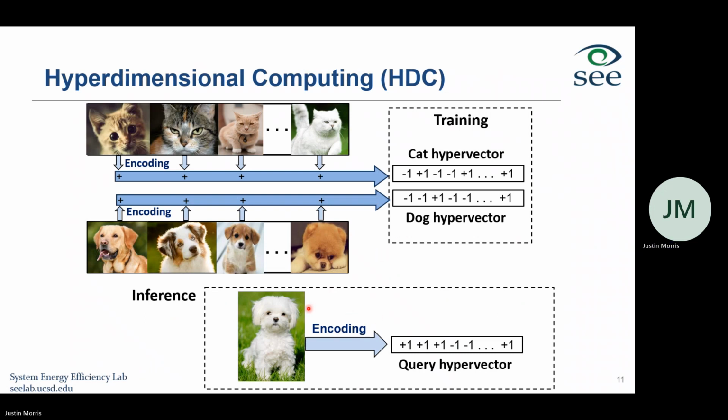So you just have the trained class hypervectors, and you need to load in some encoded query hypervector, and you're using Hamming distance as your similarity metric. You just have to count the number of mismatches. And then whichever one has the most number of mismatches is your output class. That is the basis of your final project.